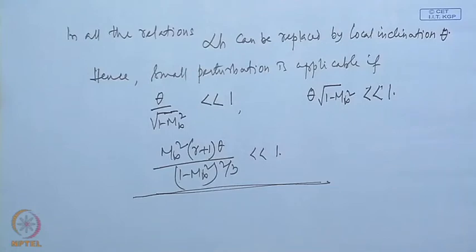Also, we have seen that for a wave shaped wall, what would be the amplitude of the perturbation and what maximum thickness or amplitude of the wall can be permitted, so that the flow can be treated as subsonic. In particular, the perturbation has an attenuation factor, that is, the perturbation dies away as we go away from the wall.